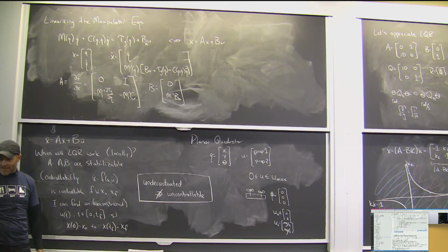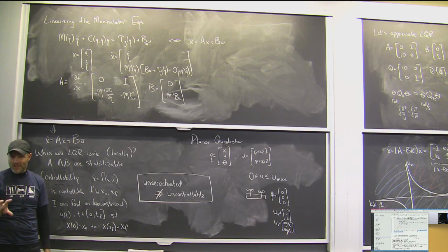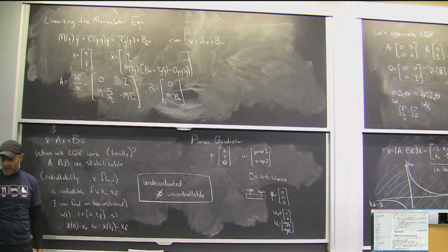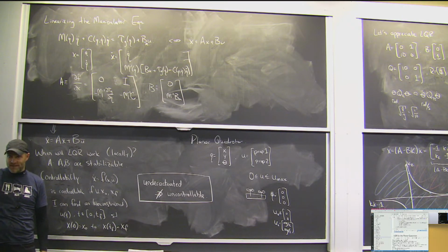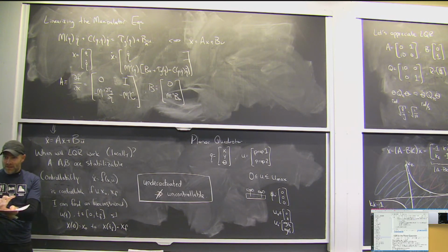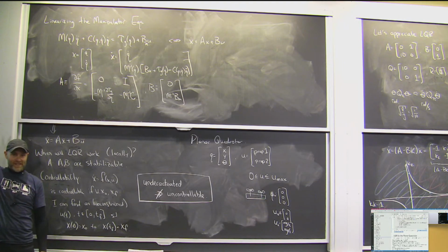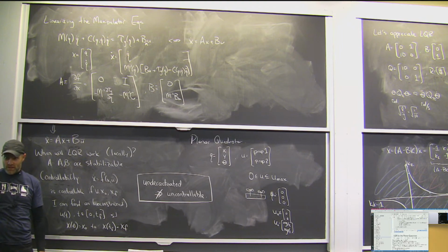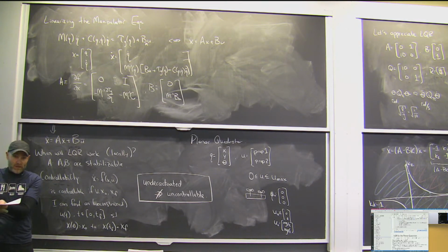Interestingly, if you had that ball-bot system and you wrote the equations of motion to allow it to fly through the air, not only would you have to deal with the fact that there's a ground, but also that system is not controllable, because you don't have any actuators that would allow you to get to arbitrary places in the air. So if you took the naive equations of motion of the ball-bot, you would say they're uncontrollable. It's only the reduced equations, where I'm always on the ground and I've parameterized my state that way, that are controllable.